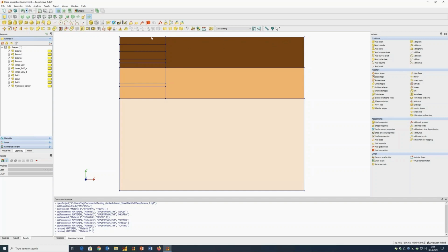And since we will be dewatering on the excavation side up to -17.9 meters, we will create a second water level like a step function. And finally, we will go through the setup of construction stage analysis, and we'll look at some of the standard output that Diana offers.